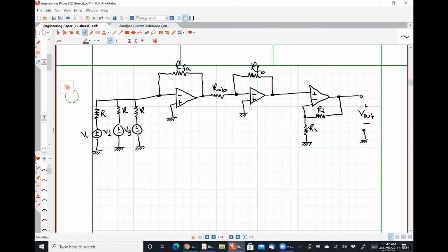So again, we're gonna start just like we started the last one, identifying a bunch of stuff, and starting at V out and working our way backwards until we get to V in. So we'll call this node VA, this one VB, oh, not VB, VX. Call this one VB and this one VY. And then again, note that this is also VY over here, and so is this terminal, because they are input terminals of the op amp.